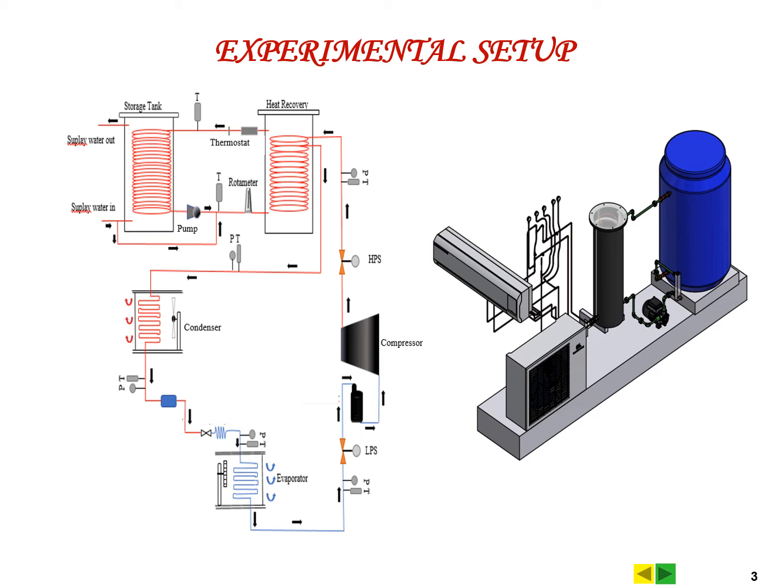For the instrumentation, we use K-type thermocouples to measure all the temperature data, and we are using a data logger with a sampling frequency of 1 hertz, stored in computer memory.